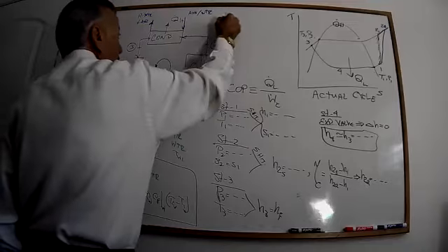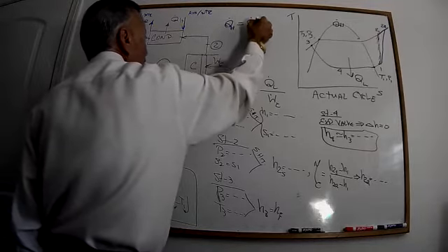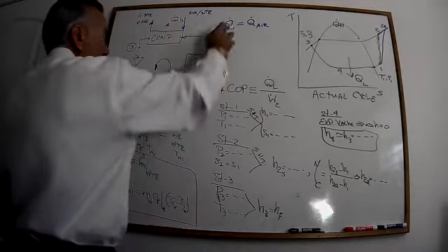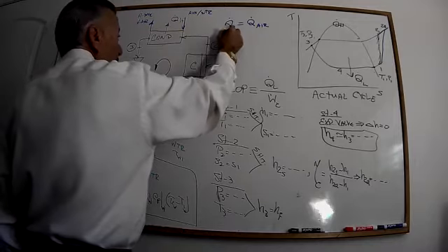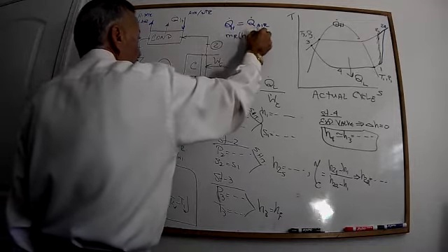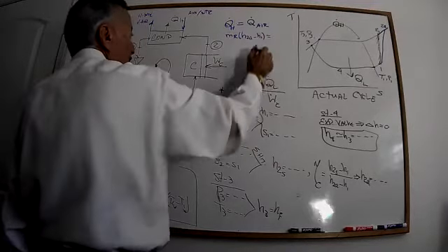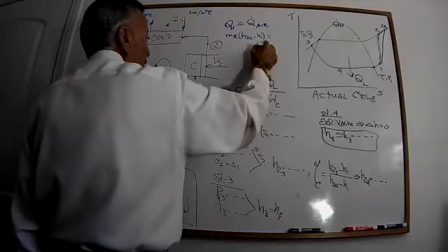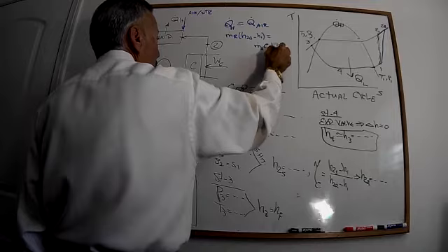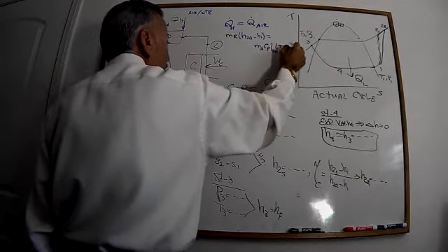in that case, our QH has to be equal to the Q, let's say, of air. Now, again, this side would be the mass of refrigerant times (H2 minus H1). On the other side, we can use the heat transfer equation, the mass of air times Cp of air times (T2 of air minus T1 of air).